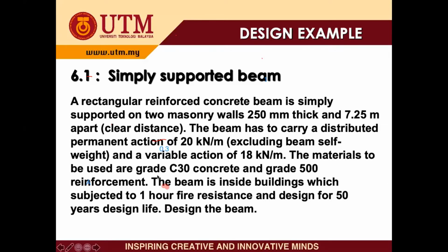The materials to be used are grade C30 and grade 500 reinforcement. The beam is inside the building, subjected to 1 hour fire resistance, and designed for 50 years design life. Okay, so for the building, automatically it is 50 years. If the question doesn't mention, you need to assume it as 50 years. So design the beam.